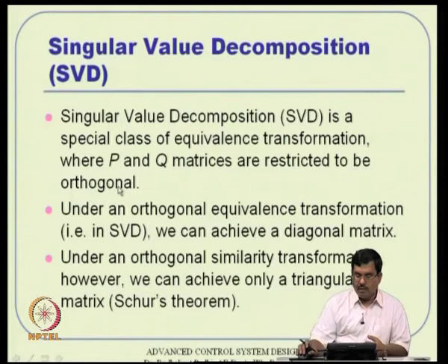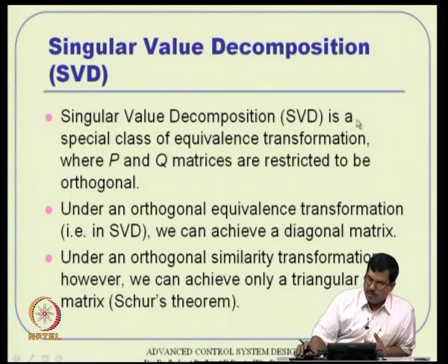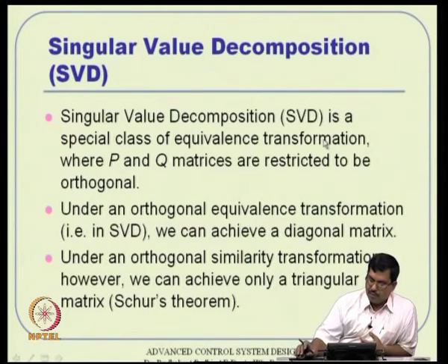So, that takes us to singular value decomposition, popularly called SVD in short form, and in fact MATLAB has an SVD command also, by the way. If you give svd and within brackets the matrix, that will give you a singular value decomposition. It will give you both P, Q and then the B matrix, everything. That is the command in MATLAB also, by the way.